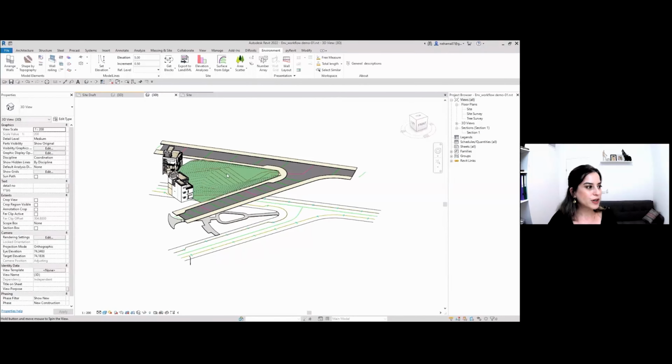So let's say I want them to show every 25 centimeters. And I already have a dedicated line style for that purpose, and click OK. And that's it. You see, I have contour lines on top of my slabs. These are actually model lines and they're dynamic. So if I change my floors, they will change with it. And so to wrap it up, let's use again check elevation by crossing 1, 2, and then 1, 2. And again, I could do it for my entire plan view. So yes, this is just one amazing workflow showing you how to create these topographies and gradings.